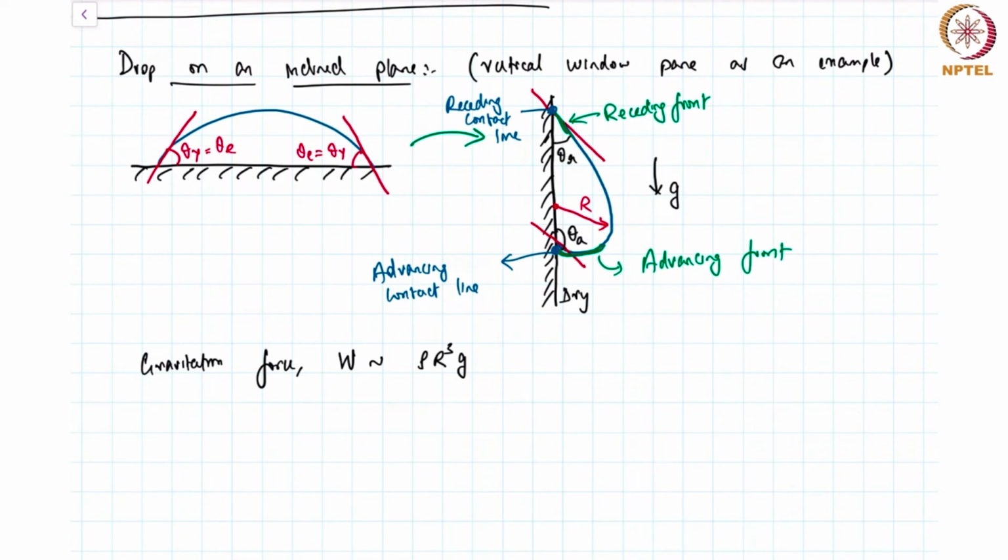That's what matters to us. And the surface tension force, or capillary force, we'll call it Fs or Fc, again scales like 2 pi r, that's basically assuming it to be the circumference of the contact line, length to scale like r, 2 pi r times gamma.